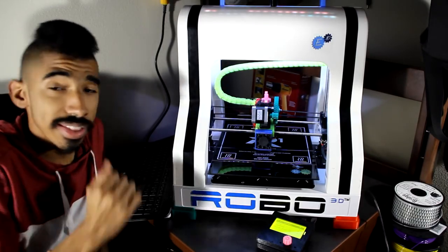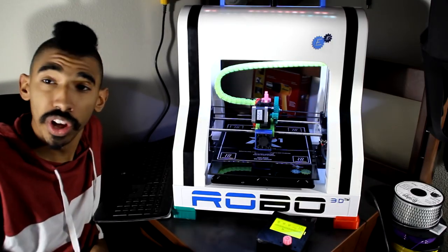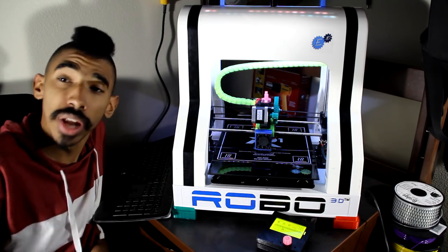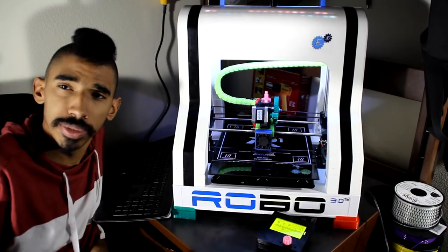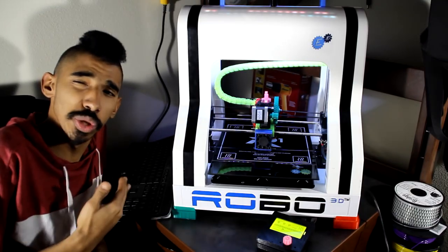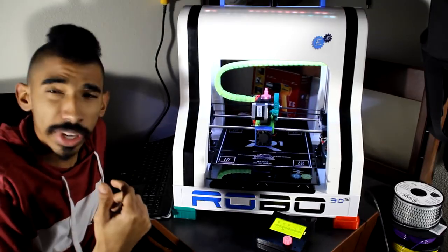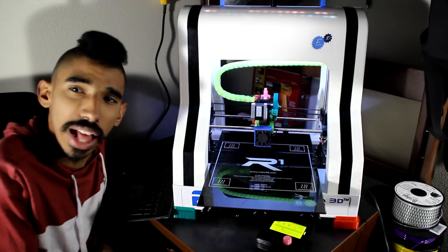Now this is Robert's favorite. We've been doing a lot of testing with this and we'll show you those in later videos, but for now I'll just show you how to run the command. So all you really have to do is just type M600. Now you necessarily can't do this with just your keyboard because there's no way to resume the command with the keyboard. You need an LCD controller.